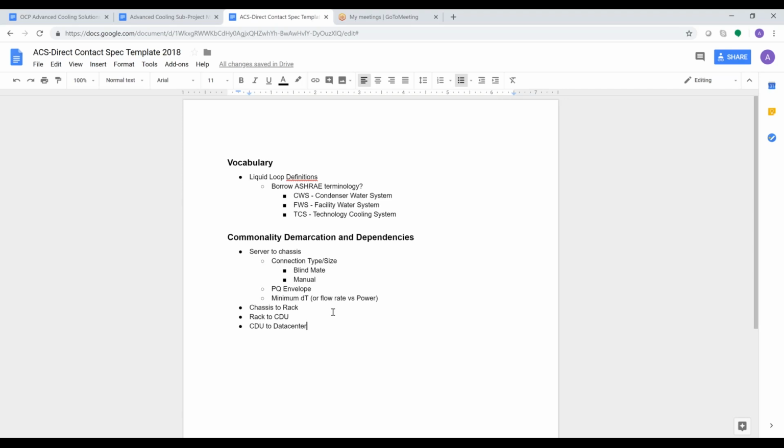I think the point is we need to carefully define that so that people know what is the box that we're drawing for ourselves. We do, and I'm trying to decide what that broader category should look like without making it too broad. Because then I think about the Liebert XCS or XDS, I forget the acronym, where there's effectively a cold plate that resides between the use space of individual servers, and they pass refrigerant through there to absorb heat from individual components. I think they use gap pads and things like that to reach down from their cooling shelves to the components. I don't want to speak for them. That's just what I recall from reading several years ago.